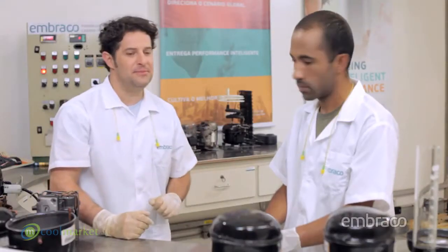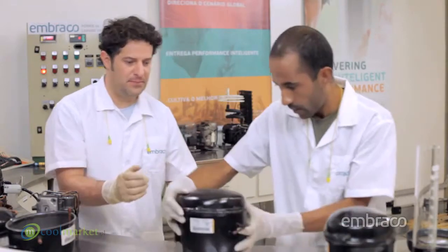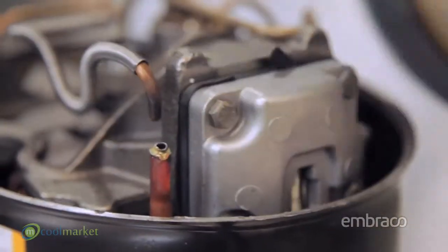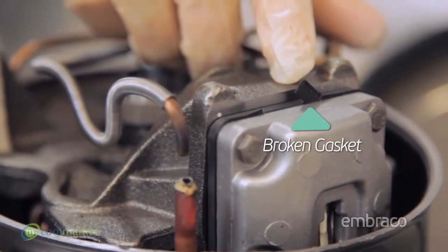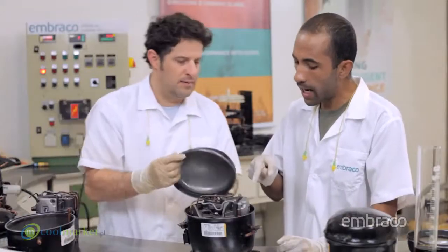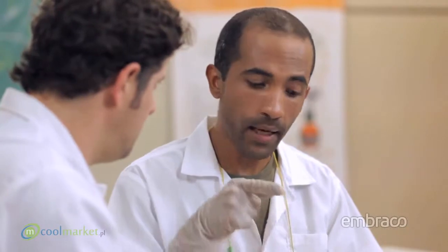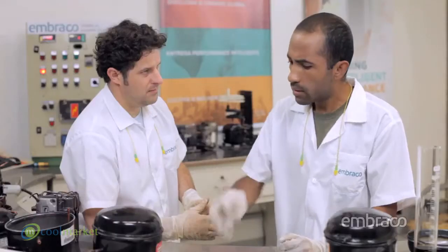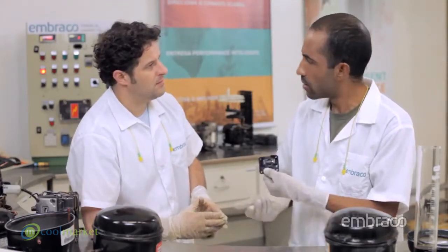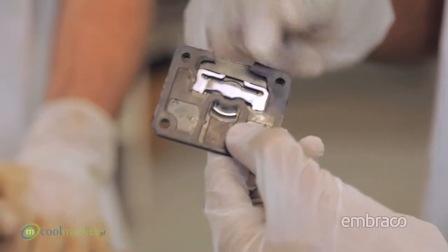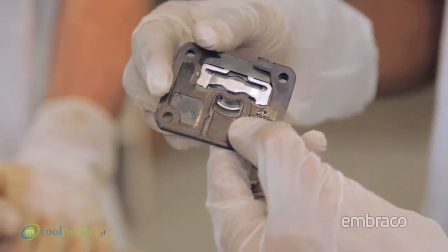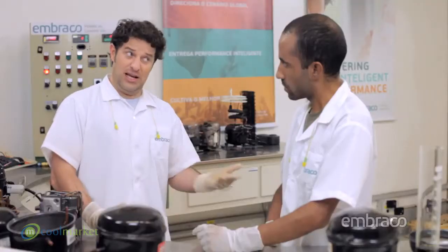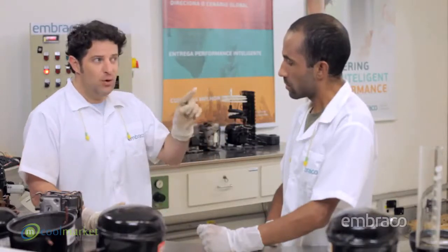Please hand me this compressor. This one? Yes, Mark. So, if the gas charge isn't done using a suitable machine, precision scale, and metering bottle, we can overcharge it. Why does the gasket rupture? Because, Mark, the gas overcharging leads to fluid return. Since the fluid is incompressible during the compression process, this generates an excessive load on the gasket, causing it to rupture. Let me show you another situation.